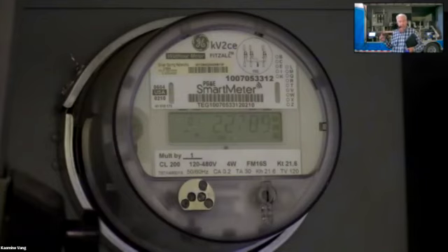But basically, let's just use kilowatts. Right now we're pulling 4.65 kilowatts. The numbers bounce a little bit. Now I'm going to slow it down 20%. Let's see how much we're using. Not to mention that was giving us a flow rate that was too high on our pump. We only need 100 gallons per minute. So we're going to let it scroll through here for a minute. First number hasn't shown it yet. I just slowed the pump down. And we're running about 100 gallons per minute like we want now.